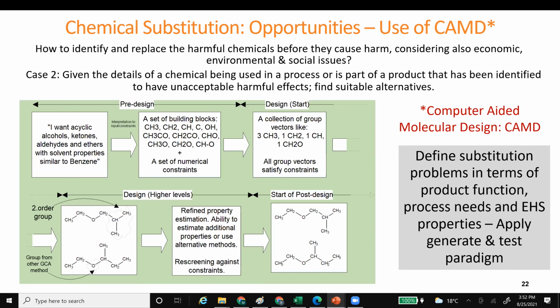And once I've generated molecules that satisfy all the chemistry rules, then I have a stable chemical molecule. And using, again, a group contribution method, I should be able to calculate the properties. And then I can check all the different properties. And if I have generated more than one chemical, I can check which chemical is good.